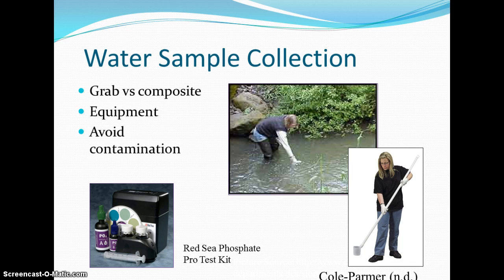On-site testing may include a turbidity tube or portable turbidimeter, use of colorimetric testing field kits for nutrients or other parameters, or pH test strips as examples. In many cases, a minimum of 3 replicates are desired, as 3 is the absolute minimum number of samples needed to report a mean value with associated variance.